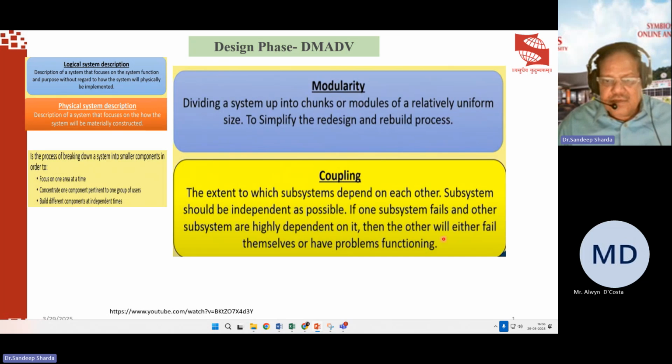That is coupling, and we also use it with a motor and a pump. The motor drives the pump, and the coupling, instead of damaging the pump and the motor, both connected with the shaft, takes the damage.